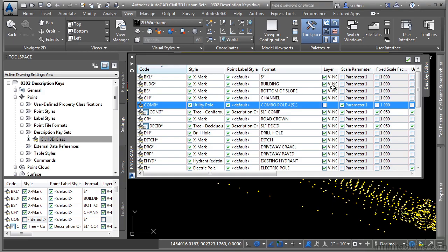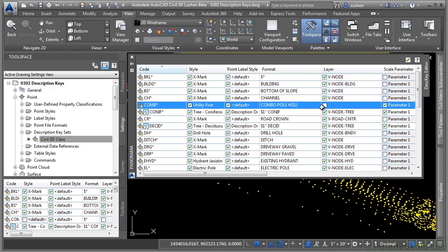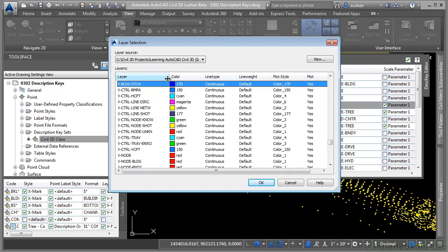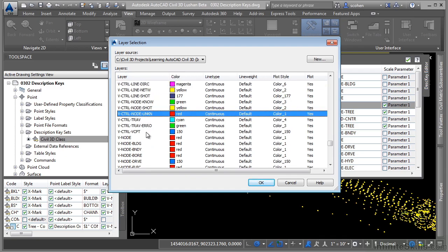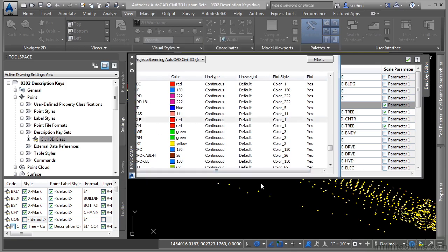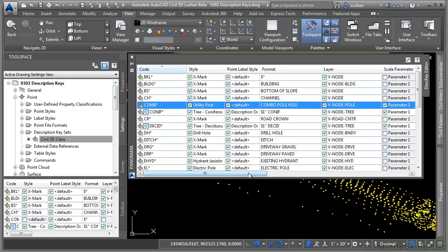What layer should this go on? We'll go ahead and click on this one here and click over here. Note that if you do not define the layer for this to go on, Civil 3D will use the style, which is okay, except for the fact that what makes this functionality really very nice is the fact that you can actually use the layer freeze command to freeze individual layers. Let's keep moving along here.